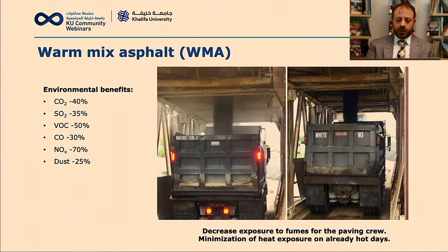This is of particular interest in this area. Imagine, go outside and imagine what's the temperature right now. We are around 50 degrees C. If you are working on site with a material that is at 170 degrees C, it's problematic. If you're working with a material that is at 135, 140 degrees C, it is much better for the paving crew.